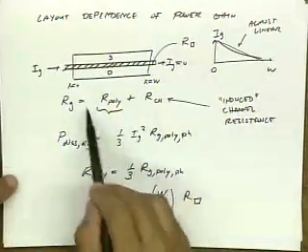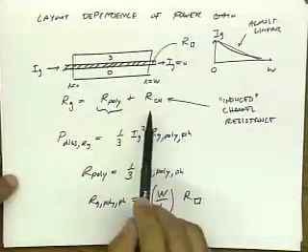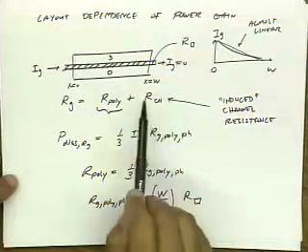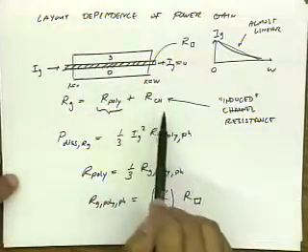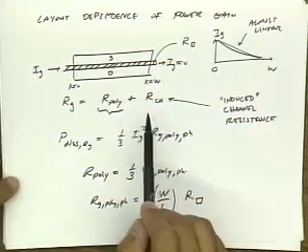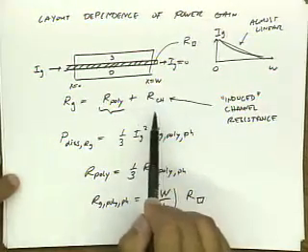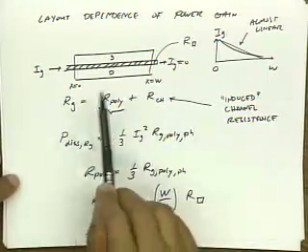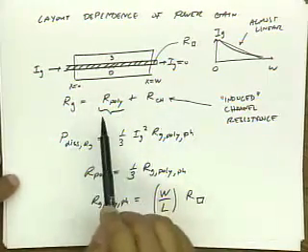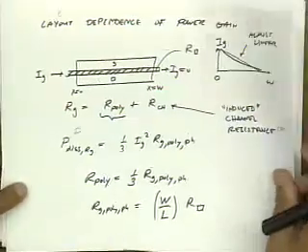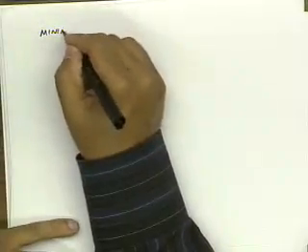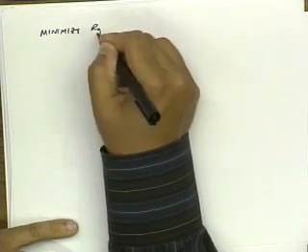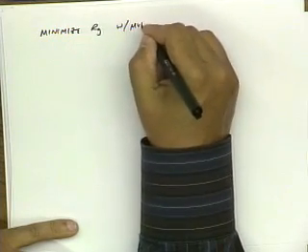Let's focus on this term. Because this term is bias dependent, I can always bias my device to have a higher and higher current and lower channel resistance. And so I can eventually be dominated by just this term here. And this term, of course, does not depend on bias. So one way to minimize our gate resistance is to use a multi-finger layout.